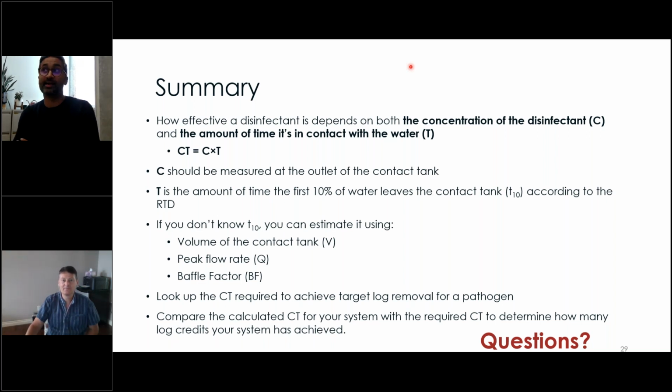Yeah, that's a tricky one. I mean, okay, so you don't have a flow meter. Ideally, you have some way of assessing how volume of water is changing with respect to time. So if your inlet pipe is entering your contact tank, or you have some way of drawing a line off of that in order to collect some volume of water, you can see how long it takes for a certain volume to fill up, depending on the size of your system. If it's a very large system, obviously that becomes more difficult to do.